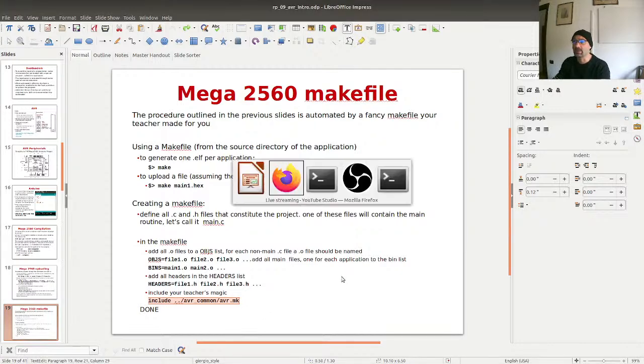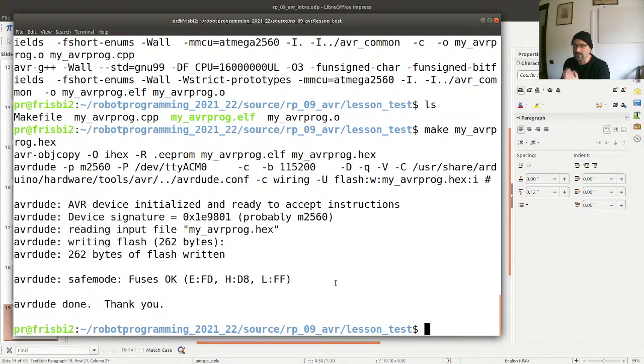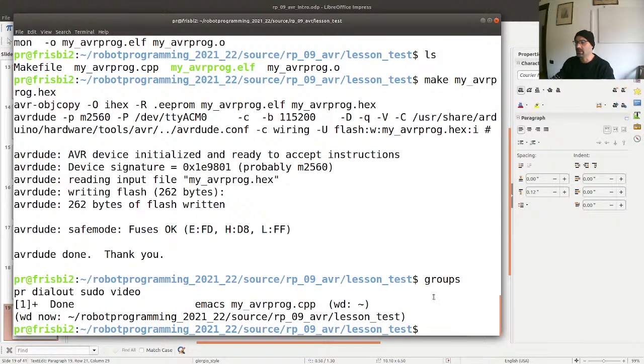with AVR. An important bit that you will encounter is that once you connect an Arduino, you don't have the permission to access the serial line. The serial line is a resource of the computer, and a standard user cannot access it. Only users that belong to the group dialout can access the serial line. So in order to use it without using root permission, which you should never do, and to be able to use the Arduino by living comfortably in your user space that doesn't make you destroy the machine, you have to add yourself to the dialout group.